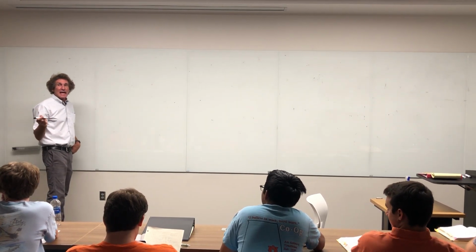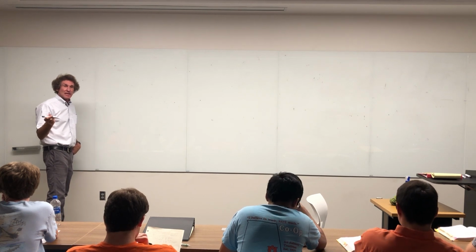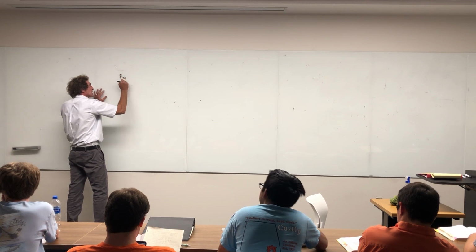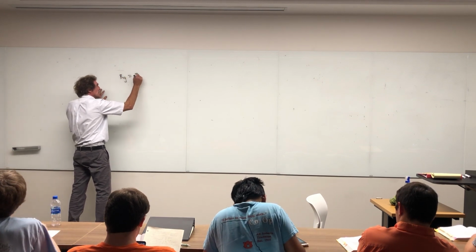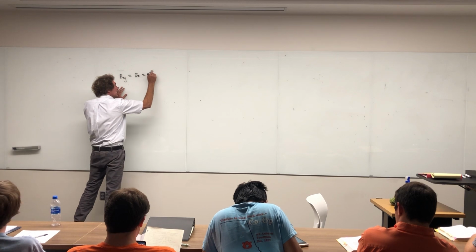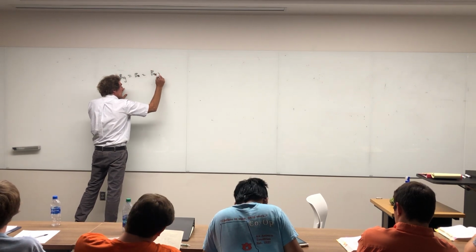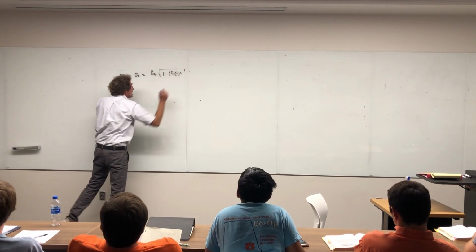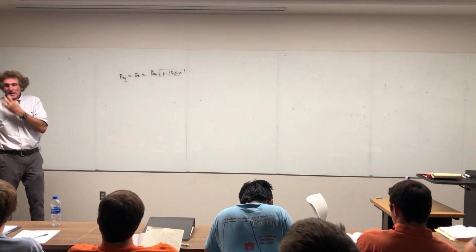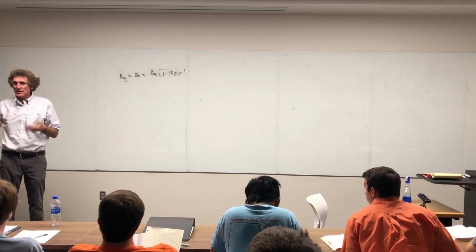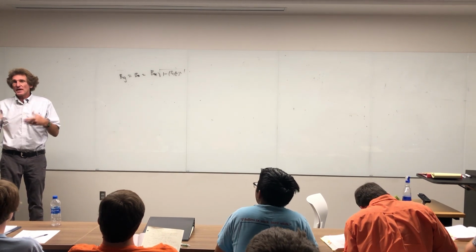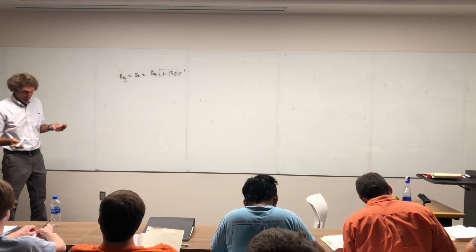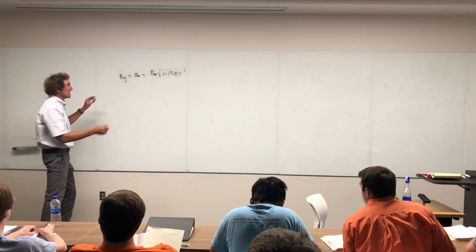Now, next thing I'm going to tell you is how to get phase velocity and group velocity. In general, first, I've got to put beta in the guide, here is beta z, right? And that's equal to beta unguided times the square root of 1 minus (fc over f) squared. I keep writing that down over and over again, and I encourage you to do that too because it'll stay with you. The more times you say or write something down, the more likely it is to stay with you. And you remember it. Now what is beta unguided, by the way?